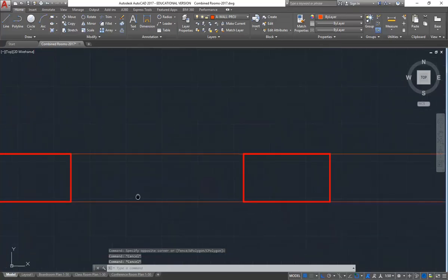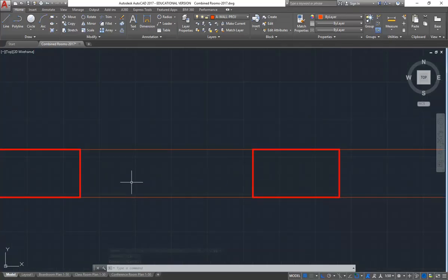And then, I don't remember the size of the window frame you've been given. 50 mil is actually standard, but I know these are meant to be metal frame windows, so they've drawn them a bit smaller. Does anyone remember the size of the frame? I think it was about 35. Okay, so I'll make it 35, but if it is different in the notes, use a different size.